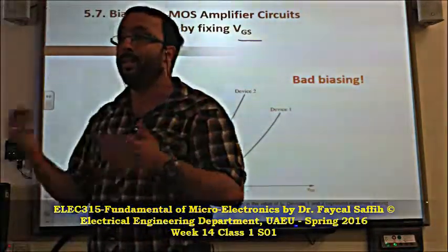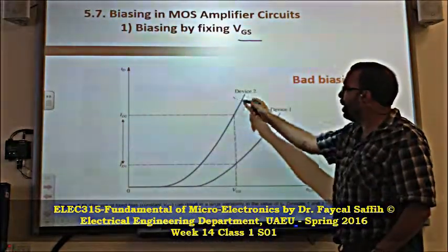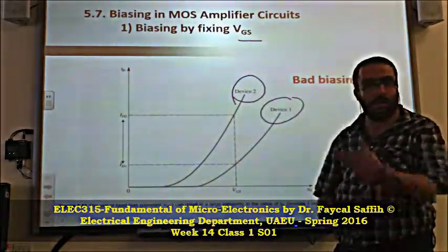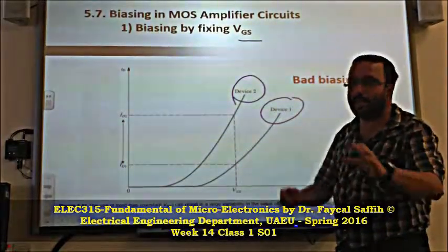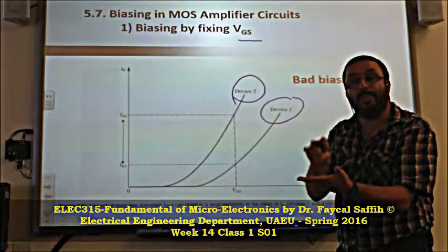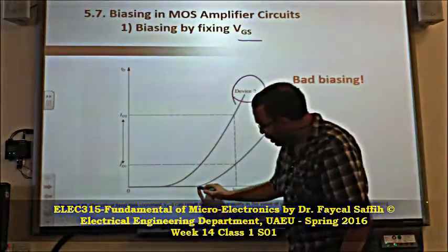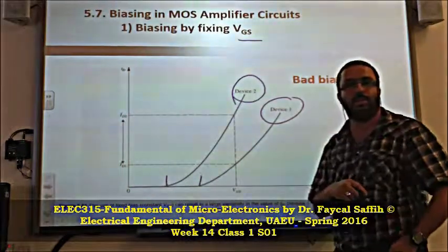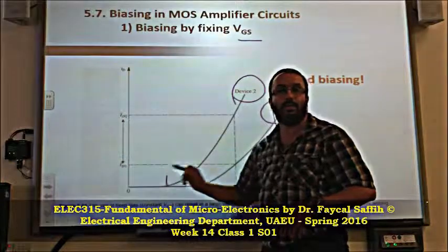There is what we call noise and uncertainty everywhere. So in that case, if I bring a device and another device of the same transistor, I'm not changing the transistor. I'm just taking the same type of transistors, bought from the same batch, but unfortunately one has a certain threshold, the other one has a different threshold. Here it's just blown up a little bit, it's too much. But usually they are very close, okay?